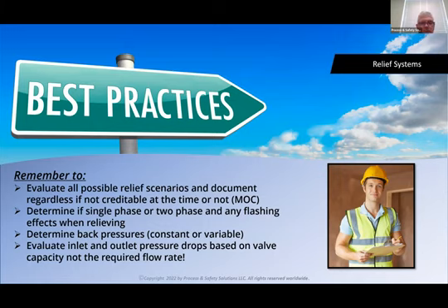Determine if you have single phase or two phase, any flashing effects when relieving. All of that is important in sizing the relief valve at the end. Determine back pressures, constant or variable, making sure you understand the effects on the different device that you're choosing to do your relief, making sure that if it's constant, that the relief valve is adjusted for that. If it's variable, maybe you need to select a different type of valve to do the relief.